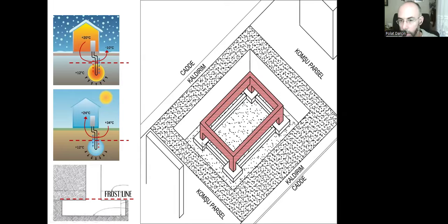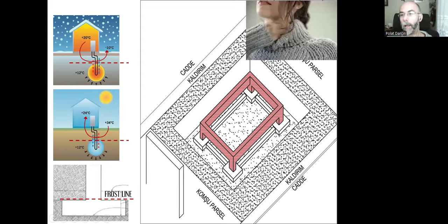As I told you, we don't need to cover the footings and the tie beams with heat insulation materials, since they are under the frost line, frost depth, there is no risk of heat transfer. So covering the foundation columns and grade beams will be enough for us. And for a proper heat insulation material, we are looking for something thick, something that has lots of gaps inside it, and in those gaps, there is air trapped.